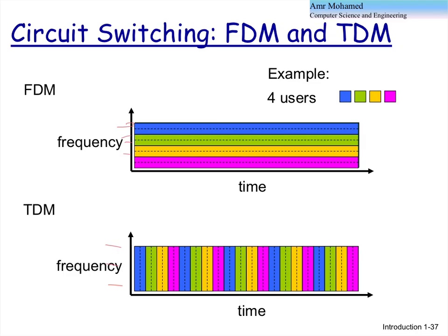In time division multiplexing, the transceiver, the transmitter and the receiver from both sides, uses one frequency range. Right? One frequency, one bandwidth. But it divides the bandwidth in time, not in frequency. So it's one bandwidth only, so the transceiver design is usually a little bit simple here.